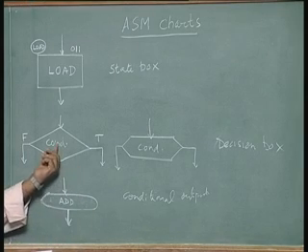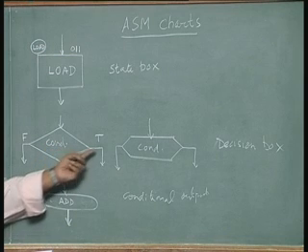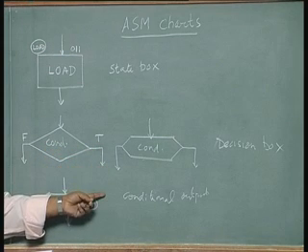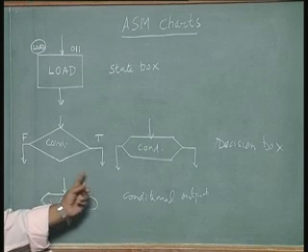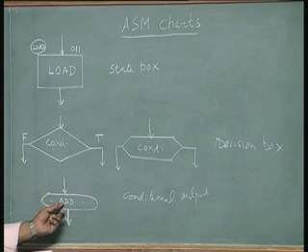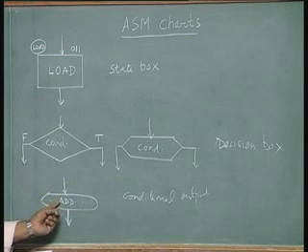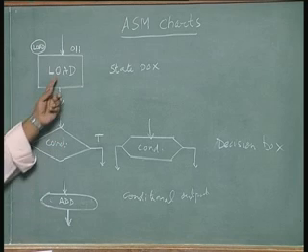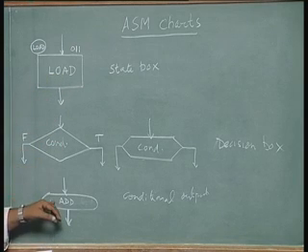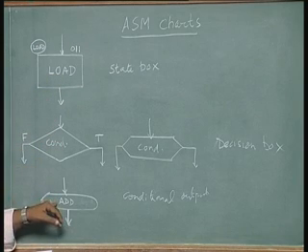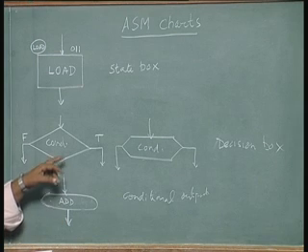So you can put a condition whether the multiplier bit is 1, and before it goes to the next shift box, you can say add. So this is an output box similar to this. We generate an output; here the output generated was load, here the output generated is add, but this is done only under certain circumstances of a condition being met.